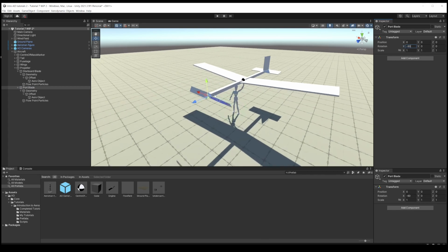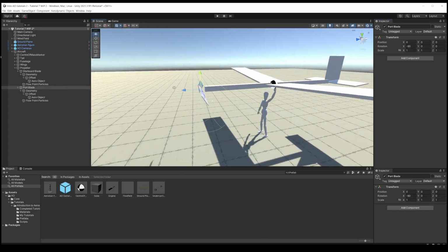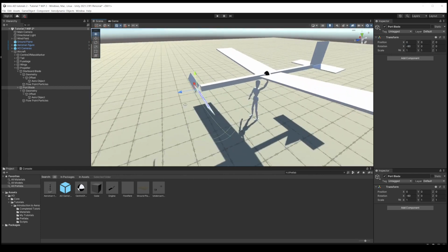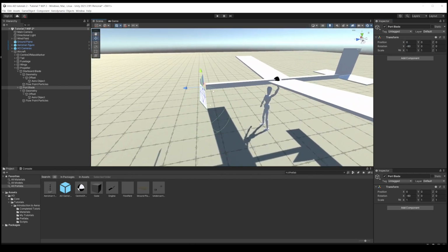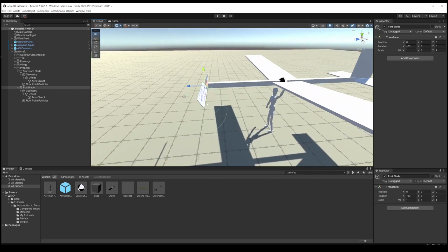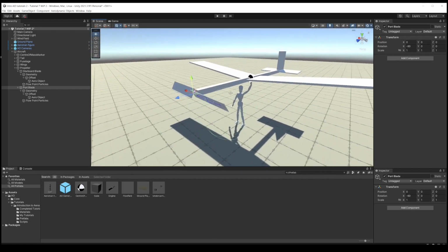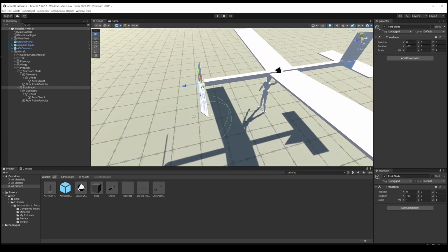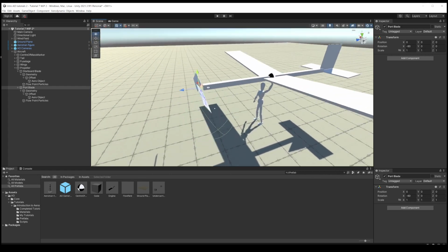And if you do anything with propellers, there's two things you need to know about a propeller: its diameter and its pitch. And the pitch angle of the blades is critical. It's a bit like the gears in a car. The angle you set these blades determines how the thrust of the propeller varies with forward speed. And sometimes if your propeller's not working, it just means you haven't got enough angle on the blades.